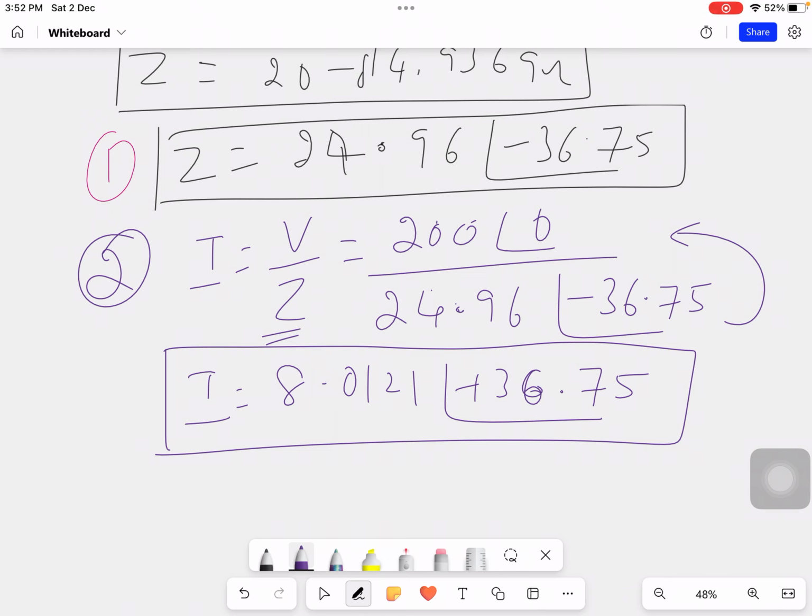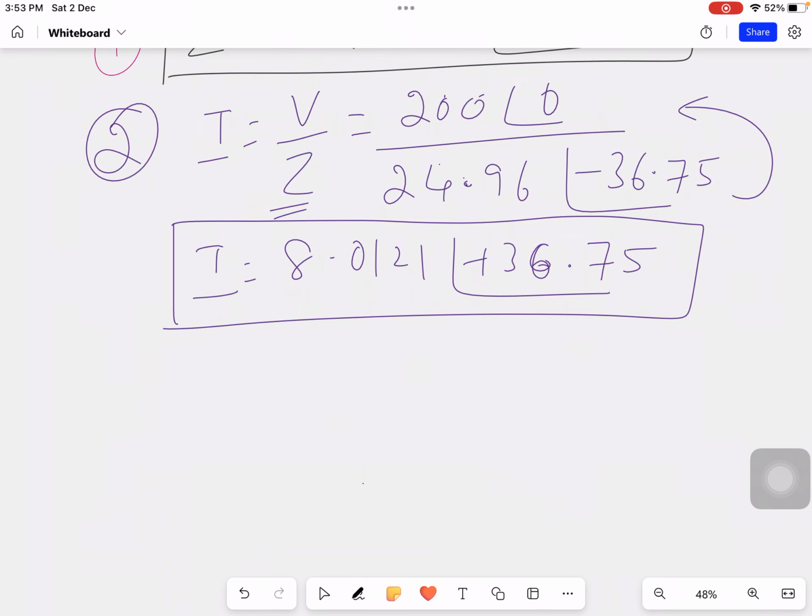Now as I said already, the XC value is greater than the XL value, so it is a capacitive circuit. Now what is power factor? What is the formula? There are three definitions: with respect to power, with respect to impedance and resistance, and with respect to the angle between the current and voltage. I will use another formula for cos phi, the third one.